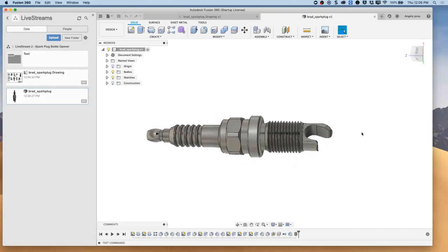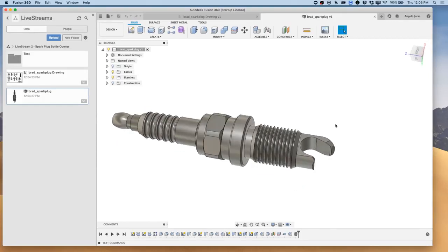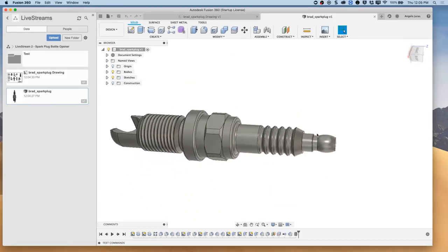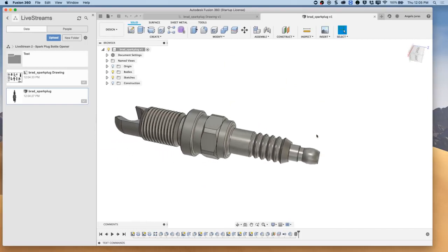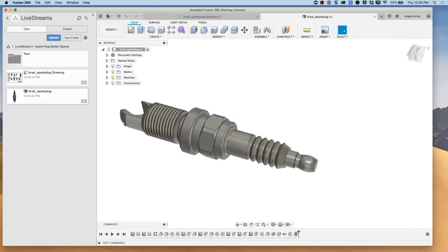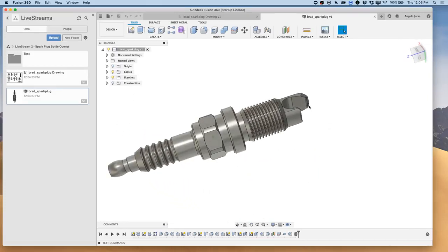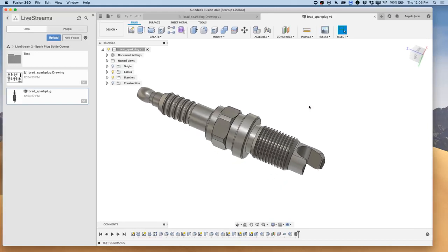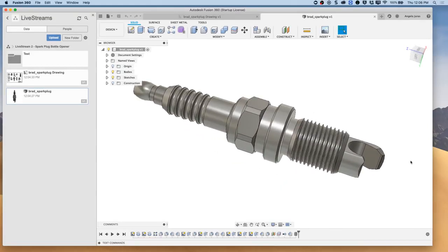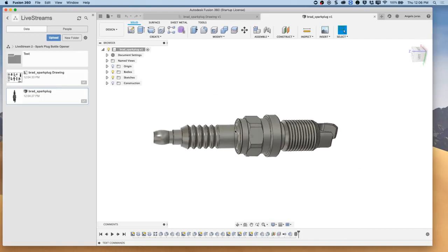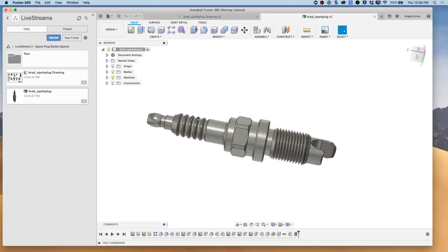on this side so that I can machine these features here for the bottle opener, because I've got milling capabilities on the lathe, so I can do that. One would think that you could hold it like this, chuck it on this end on the left, and then turn all of this and then maybe re-grab it and do something on this side. But I'm trying to do this in one operation, so I can just machine it starting here on this right side, work my way back to the left, and then part it off, and then I'll have a completed part. So that's what I'm thinking, how I would make that.